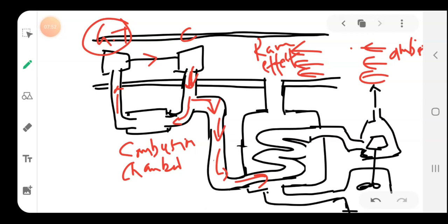So the air which has entered the aircraft system by ram effect will have a higher temperature and higher pressure. Okay. This higher pressure, higher temperature air is again compressed to an even higher pressure and even higher temperature. So this hot air is passed through a cooling chamber or heat exchanger. Some of the ram air will get bypassed through this, and